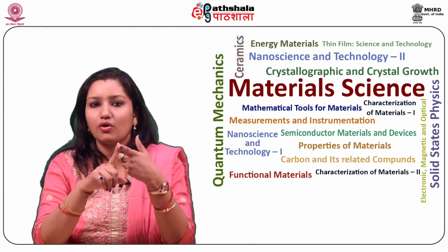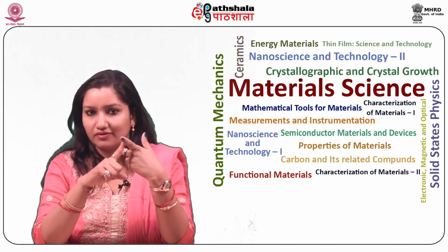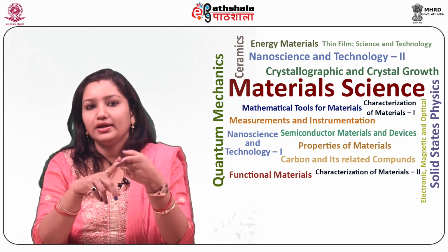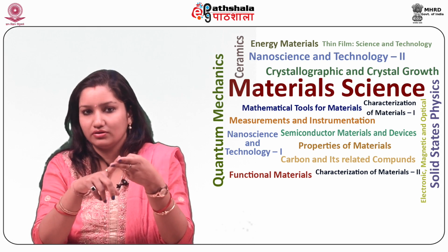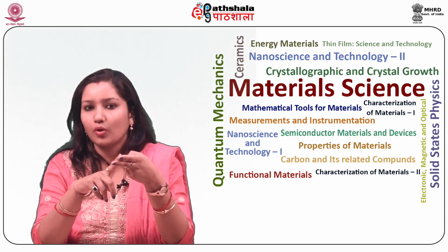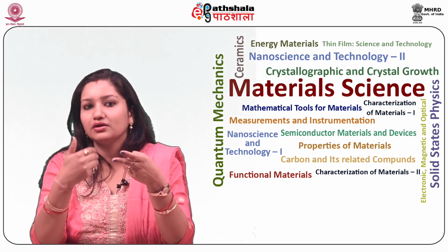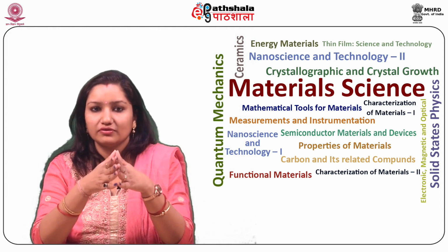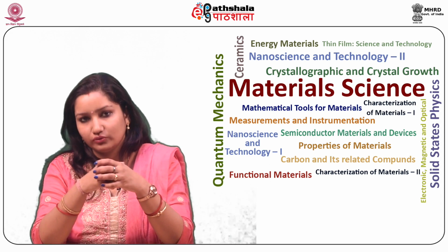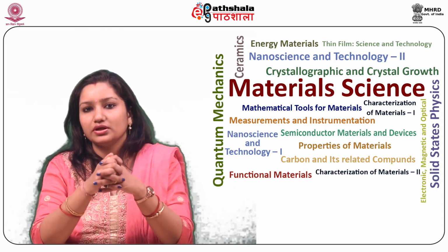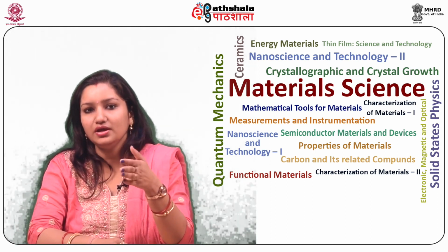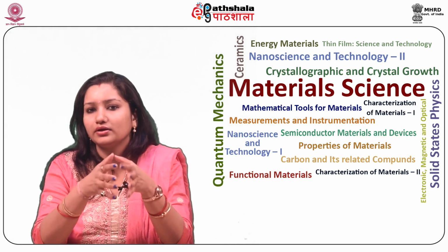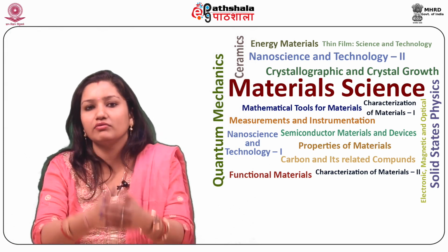Let us study the advantages of dye-sensitized solar cells. First of all, they are the most efficient third generation solar cell technology available, absorbing more sunlight per surface area than standard silicon based solar panels. Secondly, DSSCs are an attractive replacement for current technologies in low density applications such as rooftop solar collectors, where the lightweight and the mechanical robustness of the printable cell is a key benefit. These may not be as attractive for large scale deployments where high efficiency, high cost cells are most suitable. However, even minimal future increases in the conversion efficiency of the DSSC may make it suitable for some of these applications.